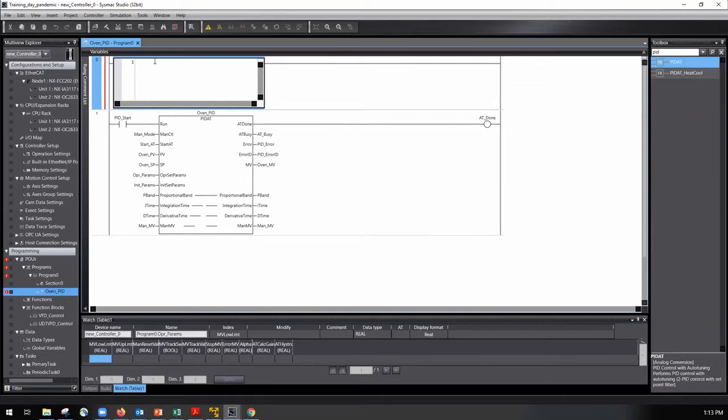And if we need to change anything, I'm going to be using constants, just hard-coded constants. We can easily online edit these if we need to. So to make a comment in structured text, two forward slashes, and I'm just going to put a little note here about what this inline structured text box does.